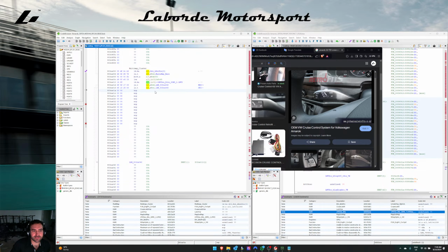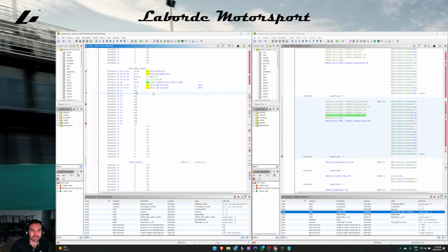Once we've checked that, we might also want to have a look at our latch variable. A latch variable is where, when you enter some function, the latch turns on, and that keeps you contained within the function. When the latch is off, it jumps you out of the function. An example: let's say we've hit the brake pedal, we hit the tip up, and it jumps to map 3 or map 2, whatever you're at.